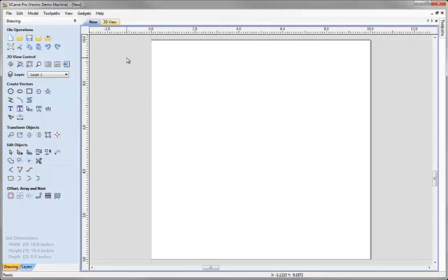Coming back to the icons, these are organised into 2 main areas. When we're doing our design, creating our vector layout, then we're going to use icons on the Drawing tab, and this is what's displayed by default when we first opened our new part. You can see that on the left here. All the icons on this tab relate to us creating the design element of our part.